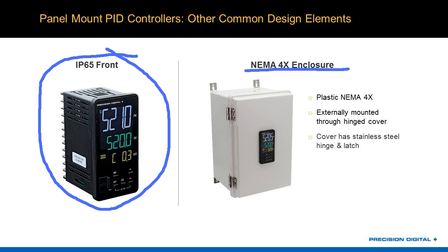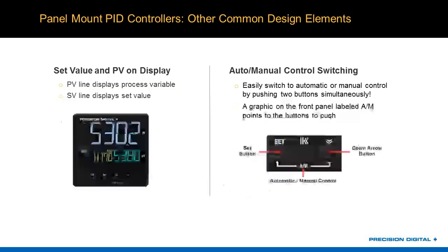However, it is worth noting that Precision Digital offers NEMA 4X enclosures you can put these in, so while obviously this is still only IP65, NEMA 4X, having seen the testing done, I would say NEMA 4X is superior to IP65 for water protection. And so if you're putting it in a NEMA 4X enclosure, you're all set. And so if you just wanted to put one of these somewhere, you get a NEMA 4X box for it, you're fine. They're two different standards. They're not 100% equivalent, but as far as putting it outdoors, being proof against water protection, if you put it in a NEMA 4X box, you're fine. You're going to maintain that IP65 without a problem, assuming your cutouts and such work out.